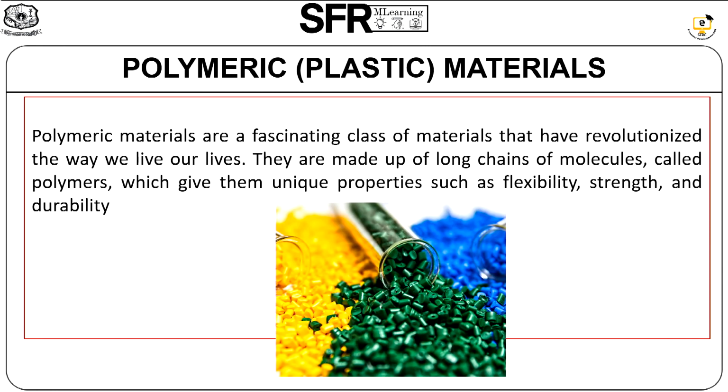So another topic is polymeric materials. Most polymeric materials consist of organic long molecular chains or networks. Structurally, most polymeric materials are non-crystalline, but some consist of mixtures of crystalline and non-crystalline regions. The strength and ductility of polymeric materials vary greatly.